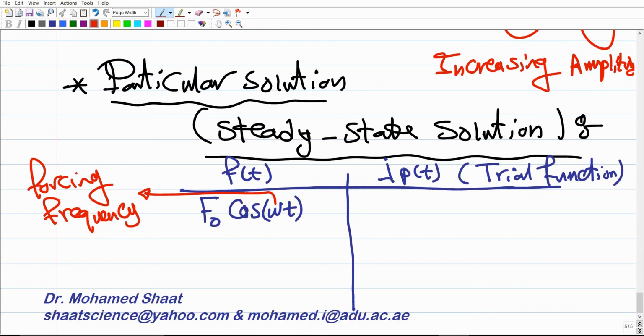The damping factor xi, omega n, and omega d are properties of the system that depend on R, L, and C only. But this omega depends on Vs, on the source, the battery, the voltage source, how much it is and its function. This is omega, the forcing frequency, okay?